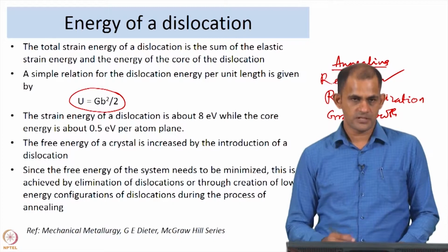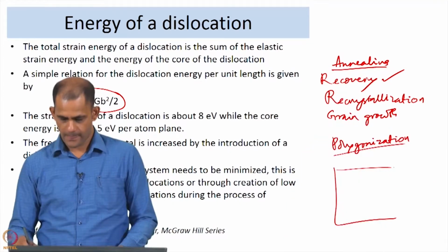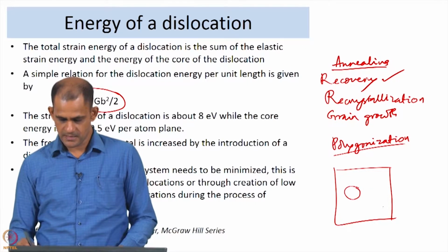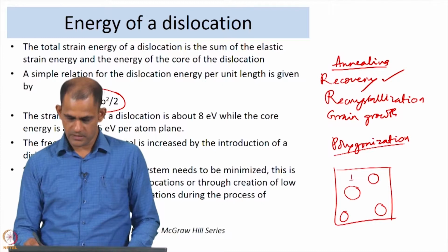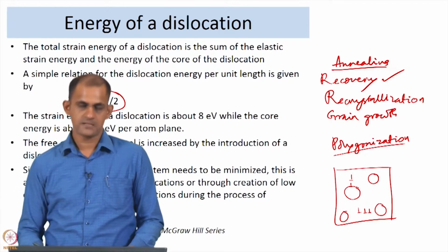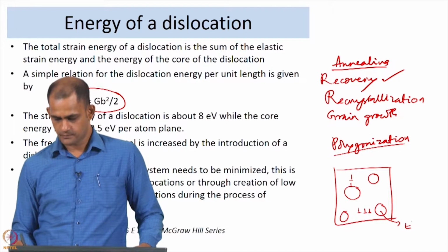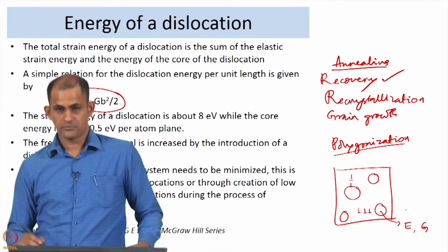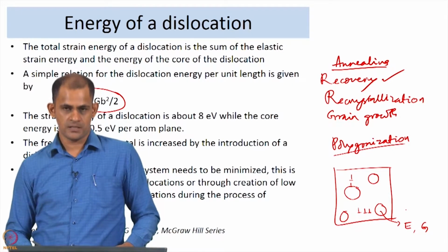That is because, when the dislocation is moving in its matrix, assume you have a composite material and this is a second phase, and the dislocation here, let me describe it as an edge dislocation. Assume some edge dislocations moving towards the second phase, and if the second phase has a higher elastic modulus, the dislocation would rather prefer not to move into that second phase.